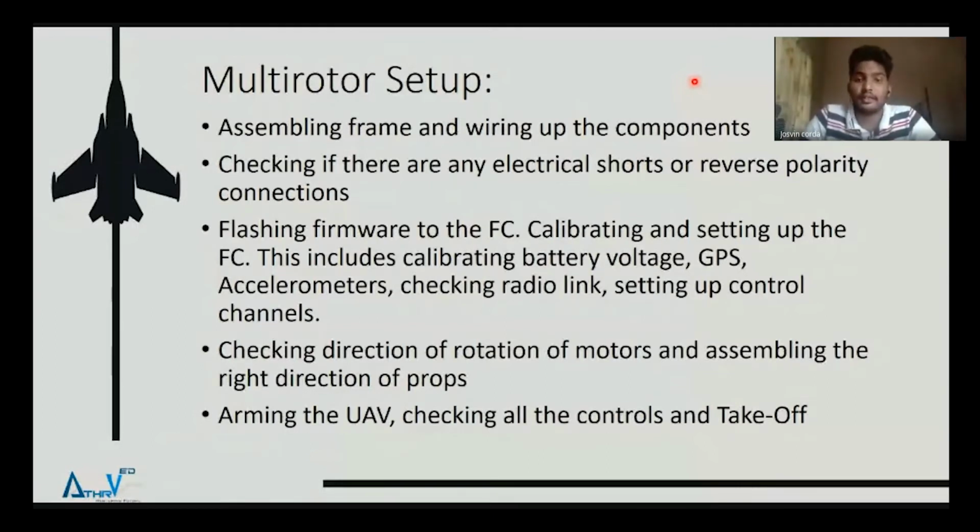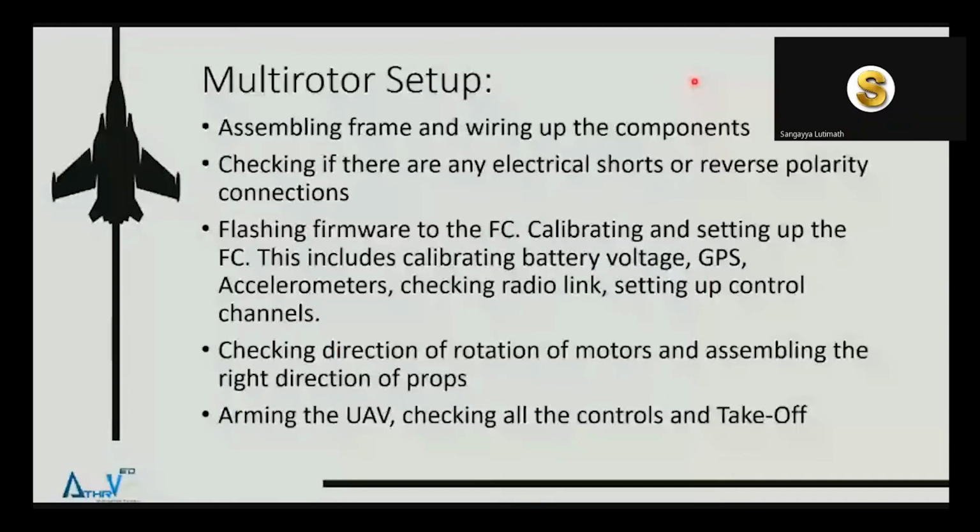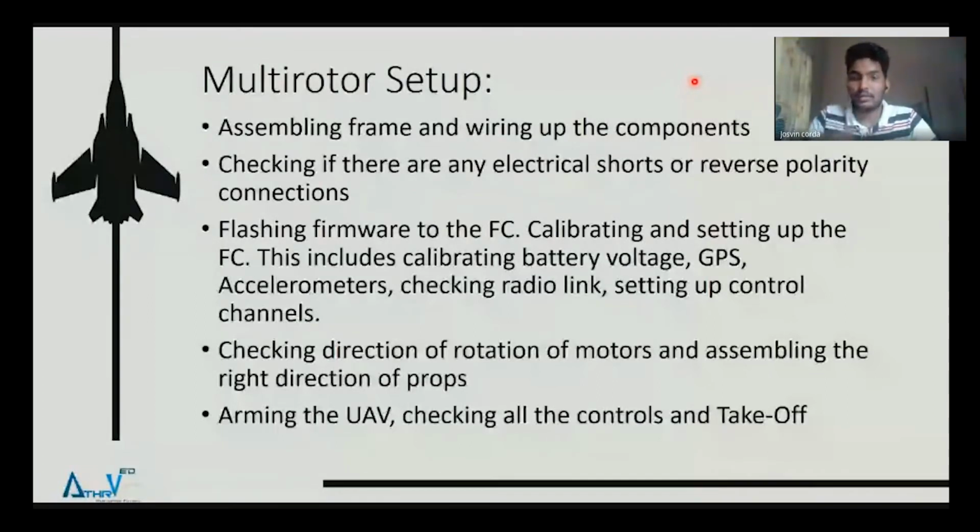And next, before you even plug in the battery, you need to check for electrical shorts and reverse polarity. If you have a short, like if a positive and negative are touching each other, or positive is touching the frame, and usually carbon fiber is electrically conductive, then it will short all the connections. And usually the consequence of a short is, if it is very close to the battery, then the battery will explode. If it is after certain other components, then it will fry those components.